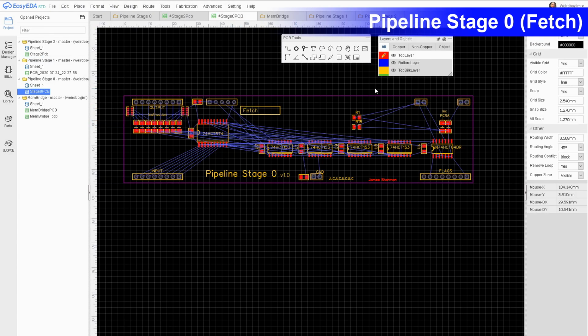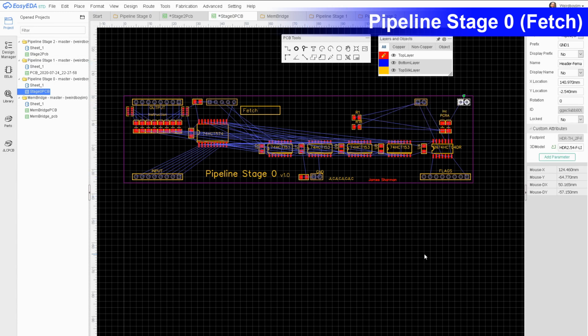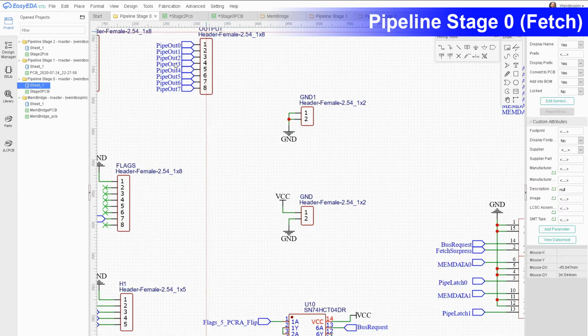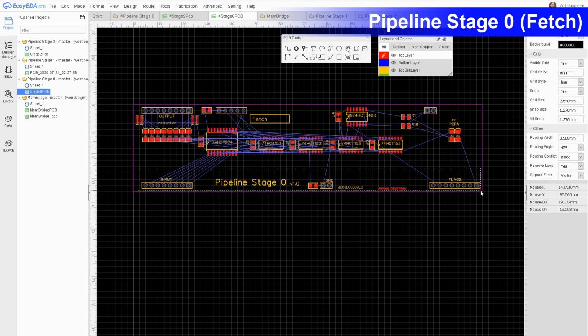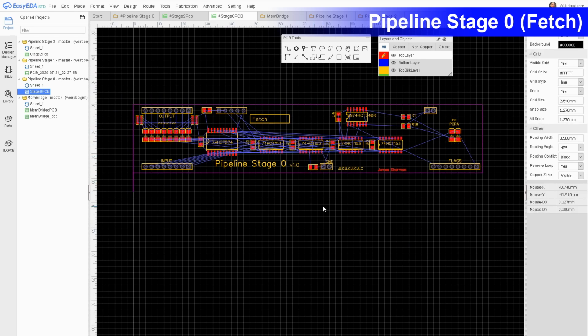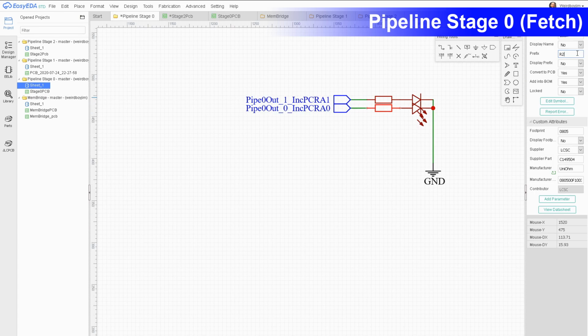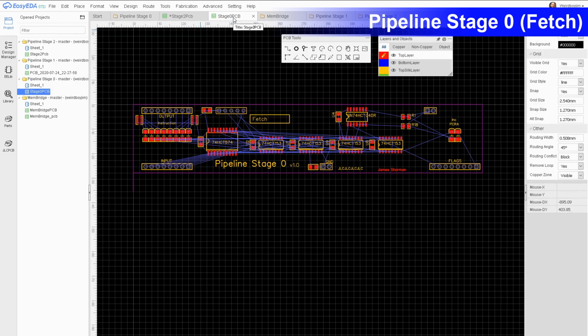A lot of my design decisions here are being heavily influenced by what I did for the next 2 pipeline stages. That is lots more satisfactory. So these line up with the least significant bits on the other 2 pipeline outputs for both the LEDs and the output lines. And the flags and all the other ones appropriately match. Should look okay sat next to them. Right, I believe that's the schematic for the fetch unit done.